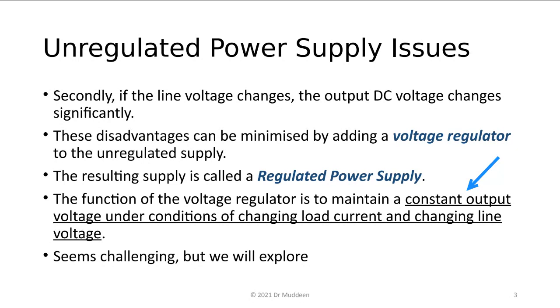Those depend very carefully on the device being powered with 5 volts exactly. There are also some devices that work with 3.3 volts. So it's important, if you are powering those devices with a power supply of any sort, if the power supply says it's a 5-volt power supply, it's supposed to remain to issue 5 volts to the circuits so that the logic levels could be interpreted properly.